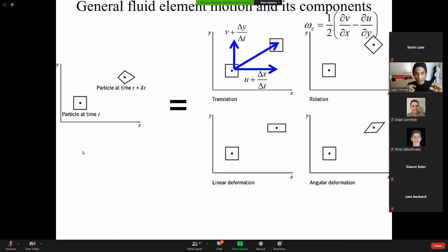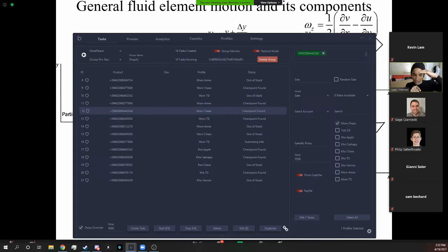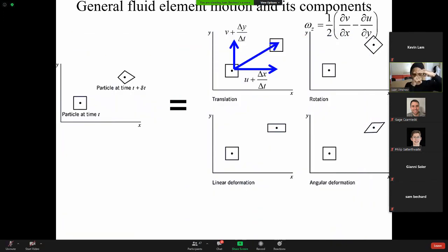So think about it. If you look at a pipe flow, is the velocity uniform throughout, or is there some sort of profile where the velocity is changing with respect to position? There would be a profile, a gradient. Okay. So if we look at this equation right here for angular velocity, this is telling us there's a velocity gradient. If that's finite, what does that mean in terms of the angular velocity? That there must be an angular velocity. Right, so it's rotational.